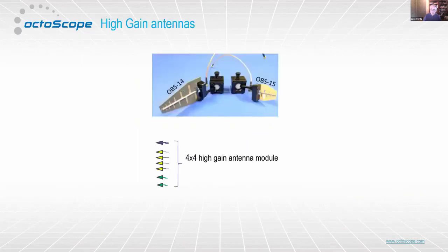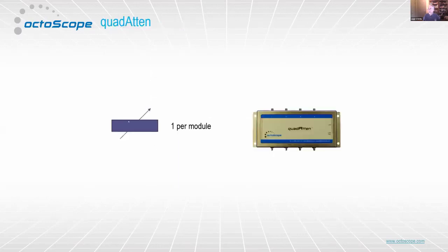You'll see antennas. The antennas are obviously used to connect the devices under test with other devices in the testbed. The key part of our testbeds is that they're over-the-air testbeds. So the device under test is almost always using an over-the-air connection, talking to some of these test antennas. And so when you look at the logical diagram, you see these little arrows. That's what that represents. As the RF energy is moved back and forth between the chambers, it goes through programmable attenuators. They look like this thing on the right, but they look like this blue box with the arrow through it on the left.